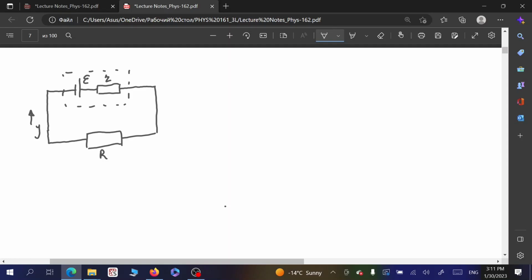So we know already that when there is a current, the dissipation of heat over a resistor will be I squared times the magnitude of resistance. Obviously, we want this to be as small as possible, not only because of the deviation of potential difference at the electrodes of the battery, but also because we don't want to overheat this battery, since the increase of temperature could have some bad influences on the performance or increase the degradation.